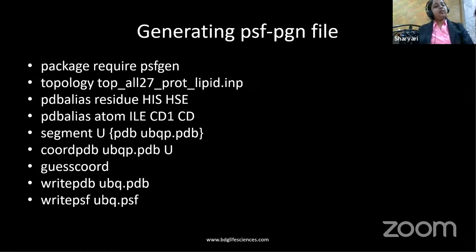Before we enter the simulation, we have to make certain changes, and then accordingly we will generate our PSF file, and that file we will provide for simulation. You can see the last two lines are important: write PDB UBQ.PDB and write PSF UBQ.PSF. These two commands tell the PSF generator in VMD to generate the PDB and PSF files.